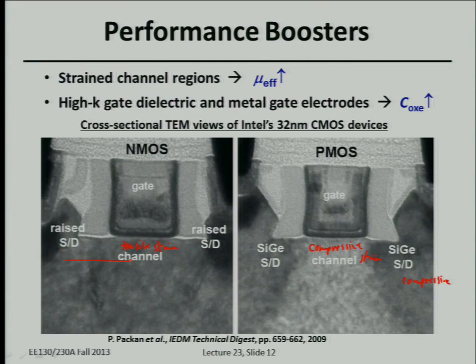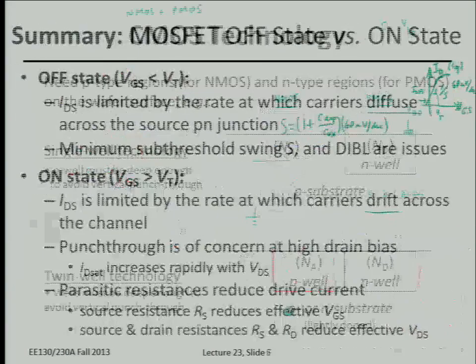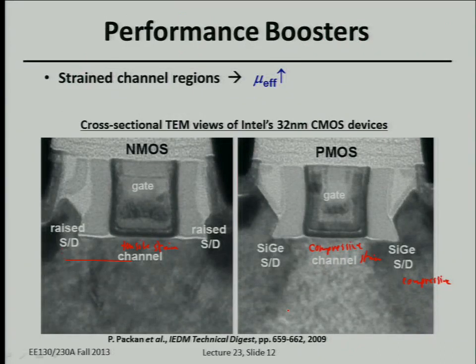In some of the most advanced technologies, you want to have thicker source drain regions to minimize series resistance. But if you make the source drain junctions too deep and too close to the channel, then that induces drain-induced barrier lowering and VT roll-off. So the short channel effects worsen if you have the deep source drain region close to the channel. So rather than making deeper source drain regions, they grew silicon epitaxially on top of the surface, so the surface of the source drain regions is raised. They're thicker, but that way you can get away with not too deep of a source drain junction. So series resistance of the source drain regions is mitigated, but you don't have really deep junctions, so you can suppress short channel effects.